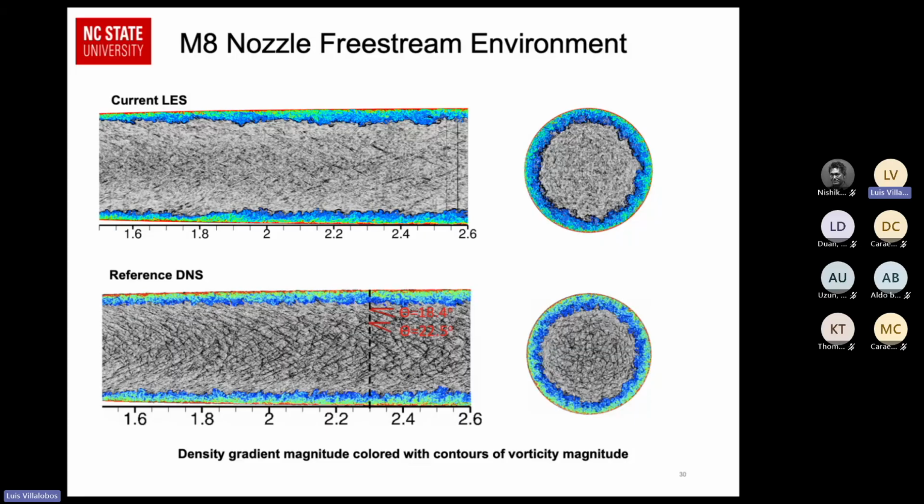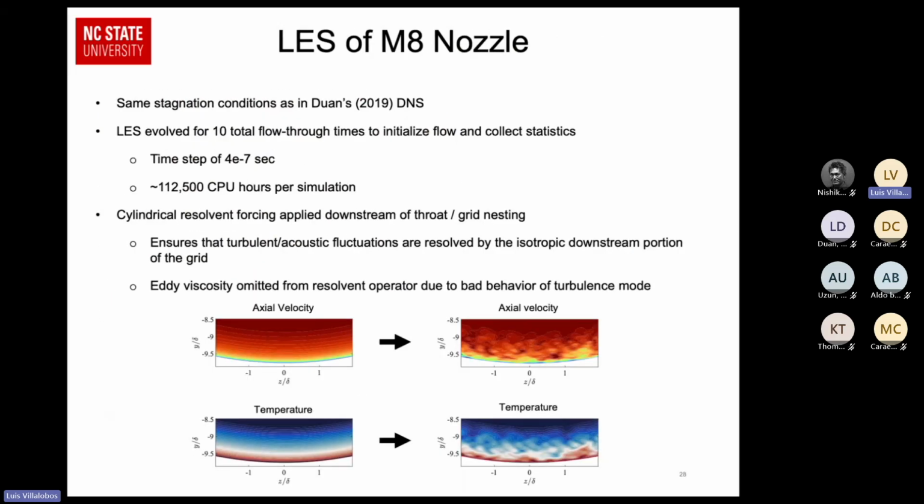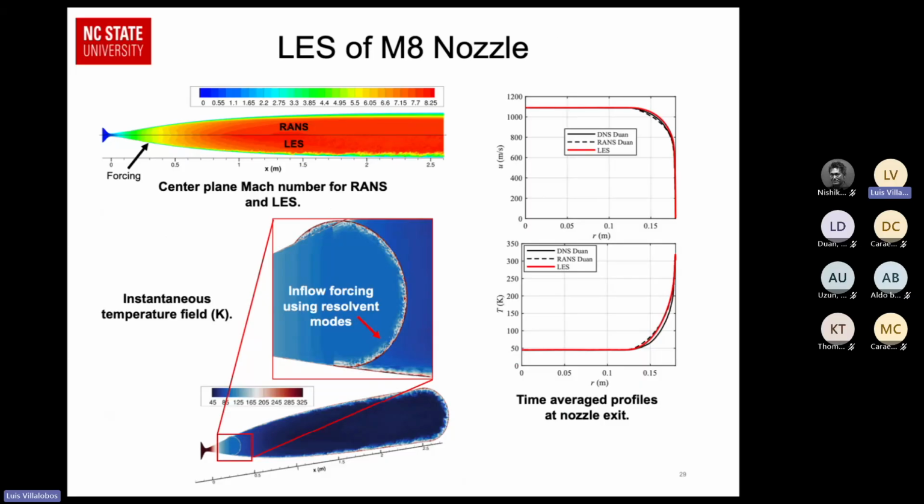I had one other question. Like you mentioned for the hypersonic tunnel simulations, the eddy viscosity thing you didn't use, right? I didn't catch why. Yeah, so it didn't matter. Is it because of the very thin boundary layer there? I'm not entirely sure, but the RANS model that we're using was excessively producing eddy viscosity, and it was introducing TKE in the outer layer of the boundary layer.